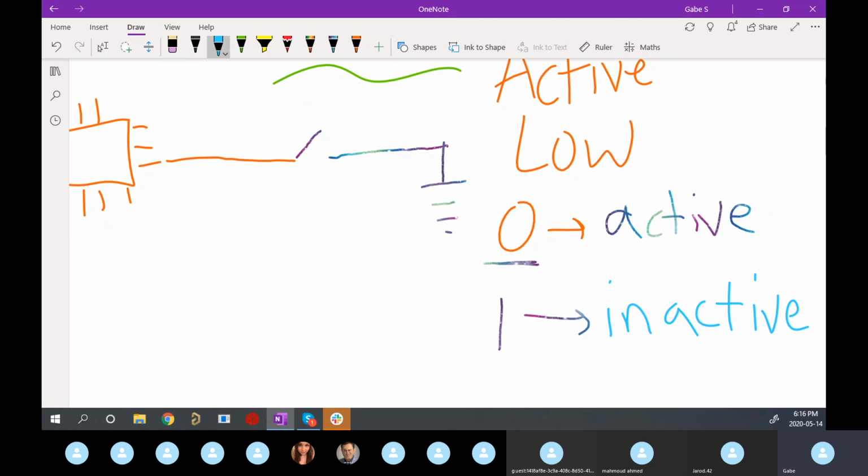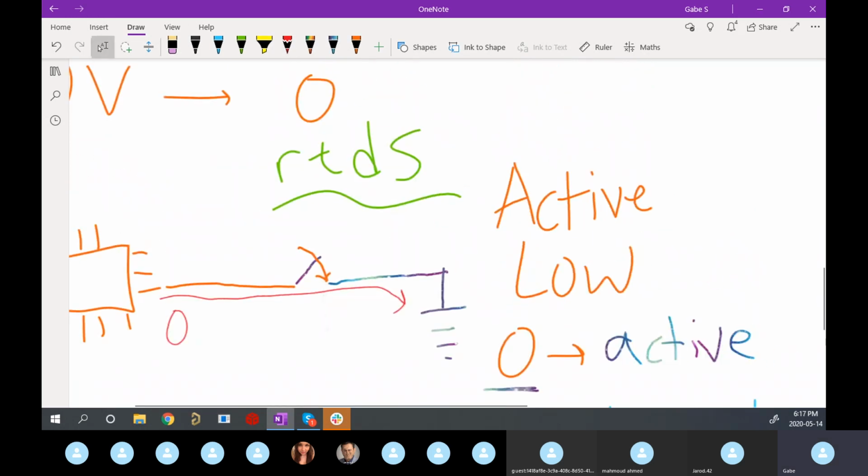So this little switch here, when the driver closes that switch, and that manifests itself just as a little toggle switch on the dashboard. When he closes that switch, this path is closed, right? So this little pin is going to be connected to ground. And so it'll read a 0. So it knows that when it reads a 0, the driver flipped that switch, and we are ready to drive.